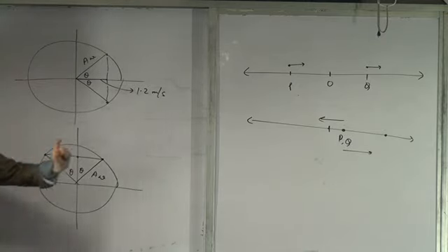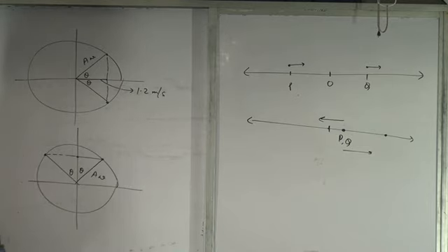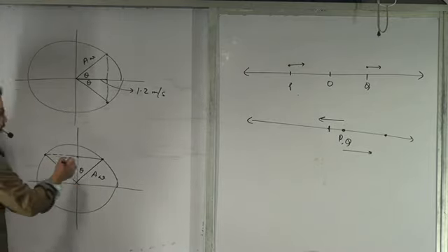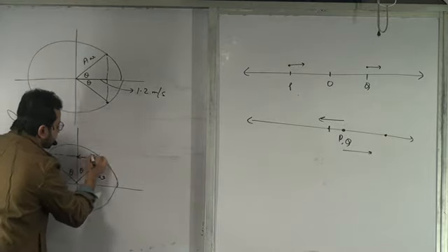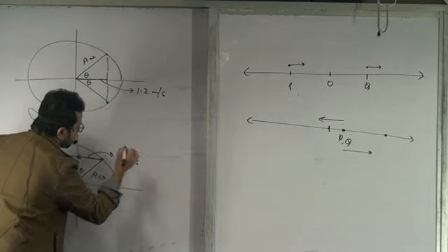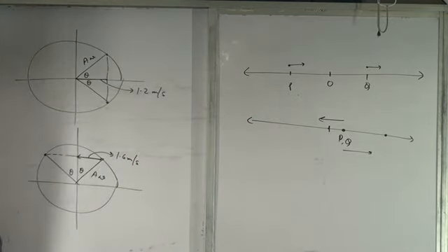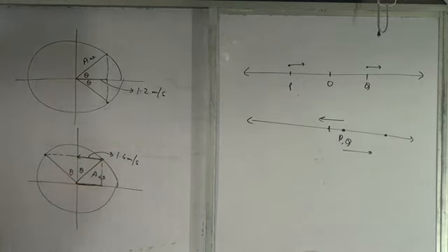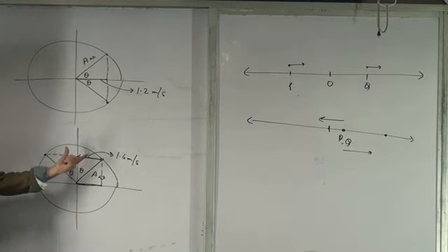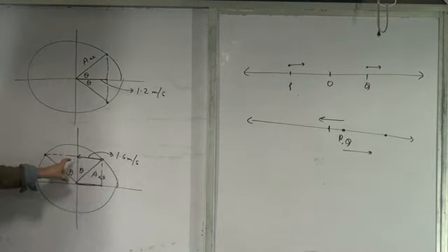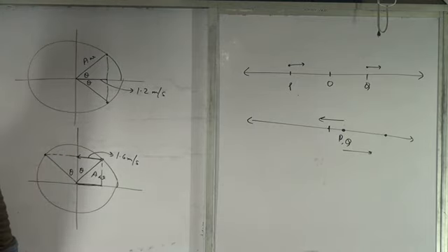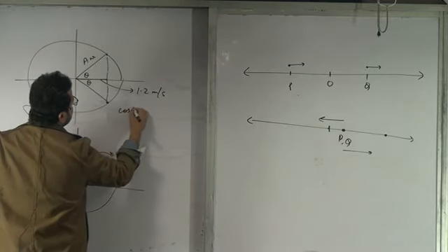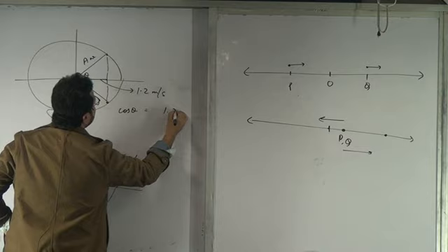Any problem? Now, what is the velocity given to you? 1.6 meter per second. Where on this one is 1.6 meter per second? No, it's the velocity. It is this one. It is the horizontal projection which is the velocity. Same as this. Same as this. So this projection is 1.6 meter per second. Not. This is the position. Is that clear to everyone? Any problem? Okay, so from this triangle, can I say that cos theta is equal to how much? Is equal to 1.2 upon Aω.